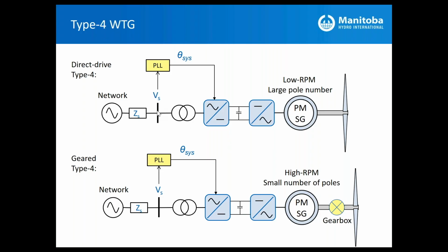Of course, there are pushes to move towards grid forming, especially for larger scale in the future, where you might have to emulate the behavior of a synchronous generator and try to energize a network, and even the machines work together in a more coordinated way and you would avoid the problems that we have been facing in the industry with weak grids and PLL robustness.